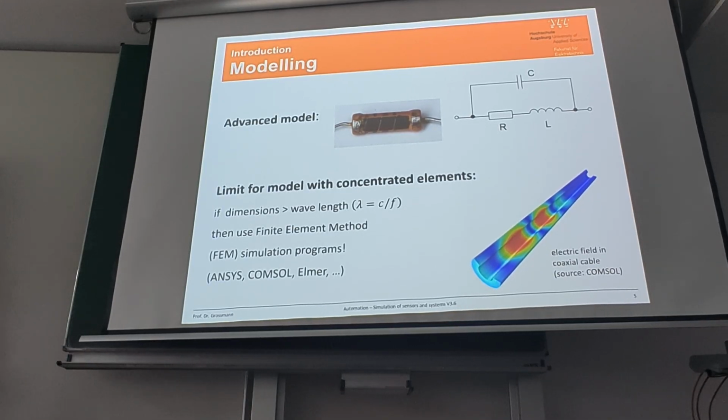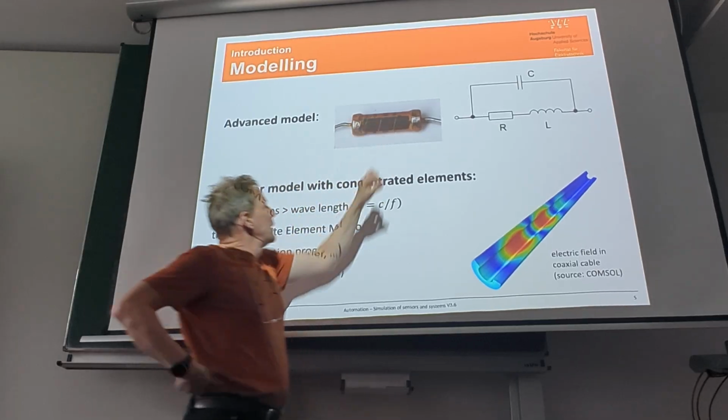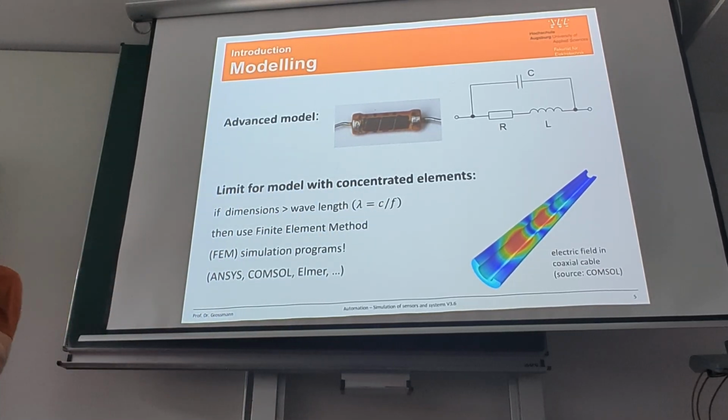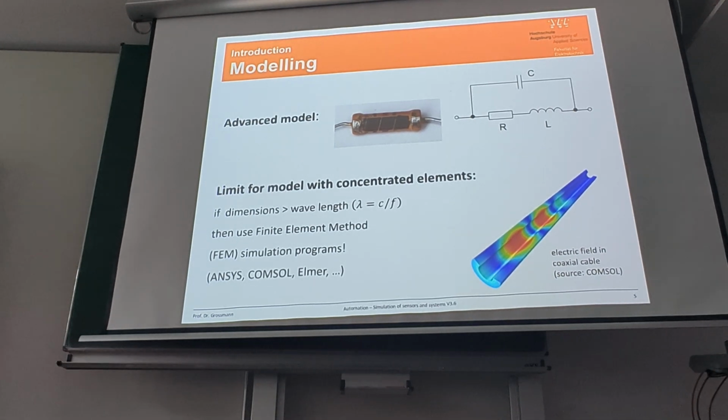So this is a conducting metal layer that makes up the resistance, but it's also a coil which produces a magnetic field, so it has an inductivity. And it seems that we can model this again with an ideal resistor and a serial inductivity.